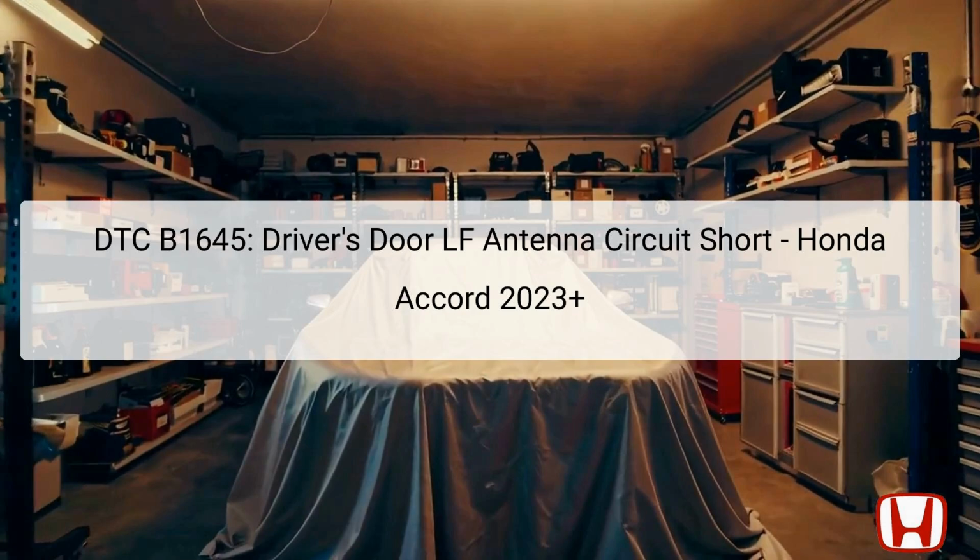DTC B1645, indicating a fault with the driver's door LF antenna circuit, is significant when troubleshooting the Honda Accord 2023 and newer models. This error typically arises when the body control module, BCM, detects an earth fault in the driver's door LF antenna line. The BCM monitors various systems in the vehicle, ensuring that electronic components communicate effectively. When it detects an anomaly in the wiring or antenna circuit, it stores the DTC.